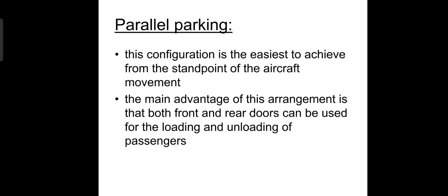Parallel parking. This configuration is the easiest to achieve from the standpoint of the aircraft movement. The main advantage of this arrangement is that both front and rear doors can be used for loading and unloading passengers.